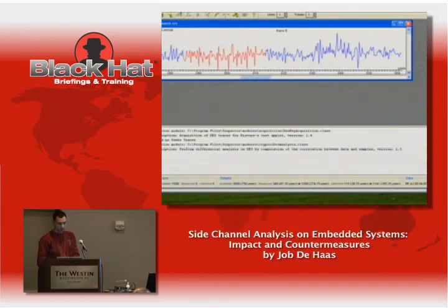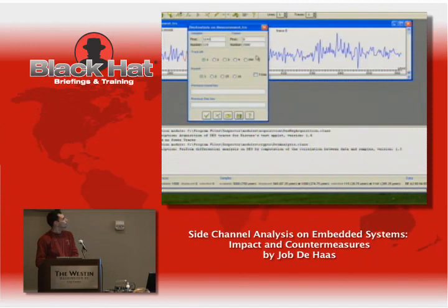Oh, now the window's here again. Try to get back again. I have to configure some things. In this case, I'm going to look at the Hamming weight, which means I'm going to look at the Hamming weight of 6 bits. And the Hamming weight is the number of ones in it, which is a measure for how many switches. If you go from 0 to the value, the ones are the ones that are switching. So if I have that happening at the same time in the CPU, because the bus is 8 bits, for instance, we can do the correlation on that combined value, and it will be stronger than if I do it on a single bit of the key.